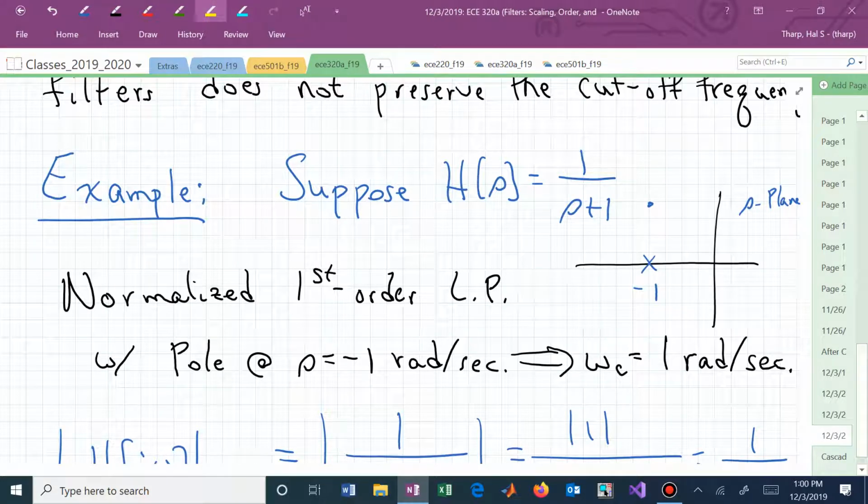We now want to know what's the value of the magnitude, and when we're looking at the frequency response, we're evaluating this transfer function along the imaginary axis. That's what I've shaded in yellow. And at the cutoff frequency, which is right here at J1, the pole will give us a magnitude equal to that distance or that hypotenuse that I've dashed in that S-plane drawing.